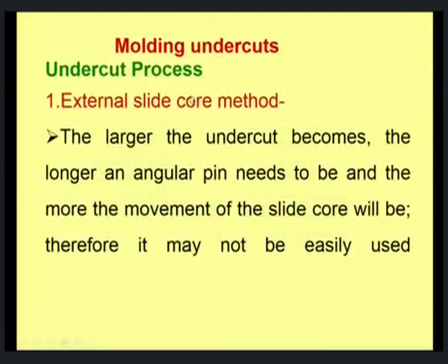This is the cross sectional view and this is the side view of a slide core. Now, the larger the undercut becomes, the longer an angular pin needs to be, and the more the movement of the slide core will be. Therefore, it may not be easily used.